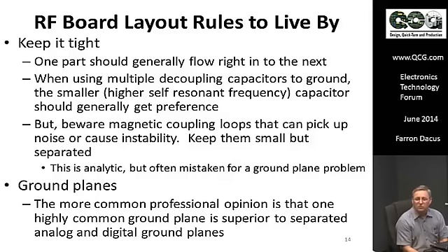Everybody's gone to switching power supplies these days, but in RF it's a very bad idea to run sensitive RF circuits straight off a switcher, so there's usually at least one intermediate stage of linear regulation, and often 2. So you may be surprised sometimes when you set up, say, a switching power supply, and then you have 2 regulators following this thing. You think you've done your homework and that's going to be a real clean supply.